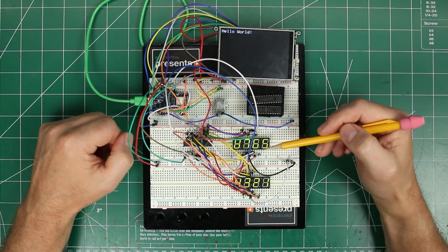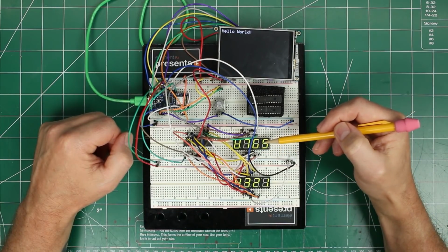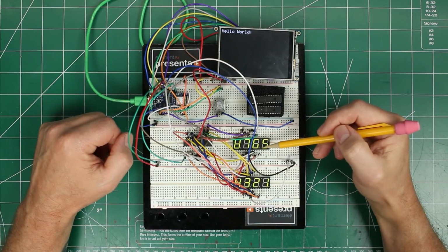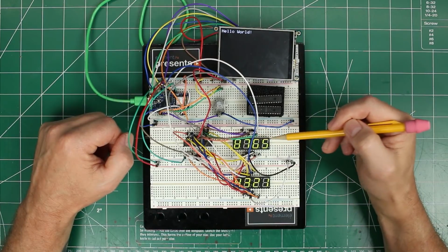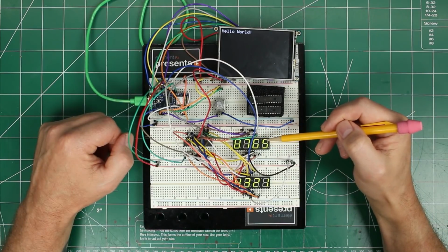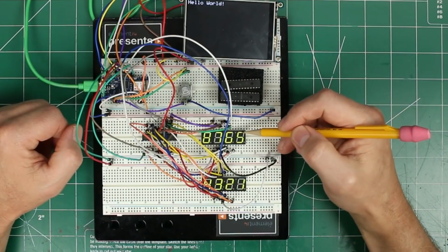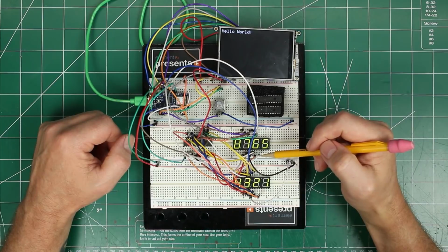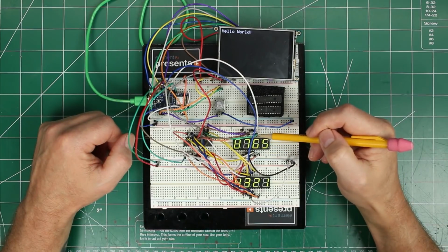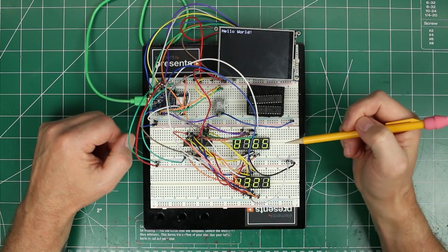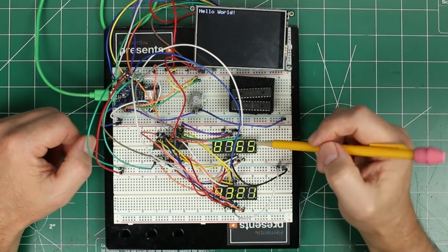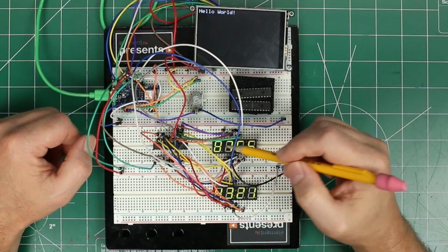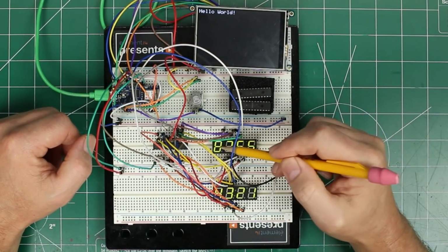These specific displays are common cathode 4-digit 7-segment displays. In this case, what that means is there's a digit pin, which is the common cathode for all of these LEDs. And then there's another pin for each one of the LEDs, which is the anode. These are labeled A, B, C, D, E, F, and G. And that works. You just pull this low, pull this high, and it'll light up that LED. The problem is that if you pull all of these low and whichever ones of these high that you need, since there's an 8 in here, every one of these digits is going to be an 8.